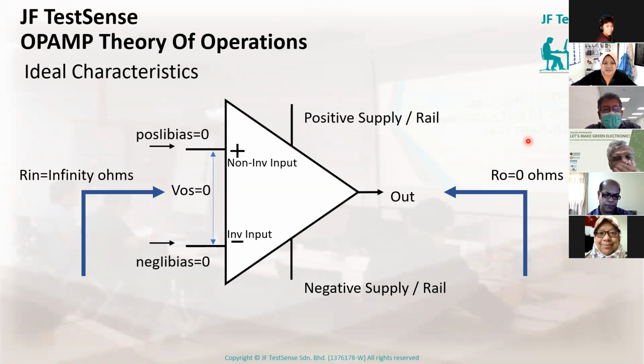We mostly consider, when you analyze an op-amp circuit, you consider the op-amp as an ideal op-amp, right? Yes. Now, what is an ideal op-amp? Basically, you see here the ideal parameters of an op-amp, right? So it does not take any current at the input. The two inverting and non-inverting inputs have no voltage differential across them, it is 0.